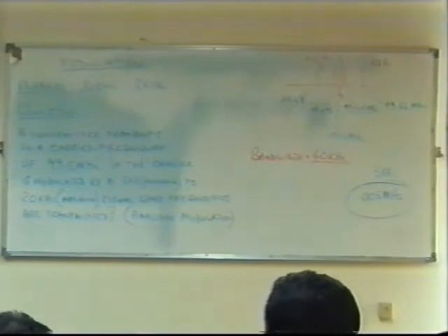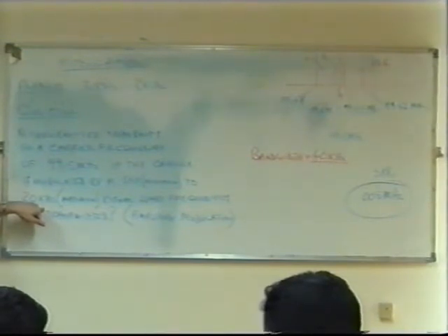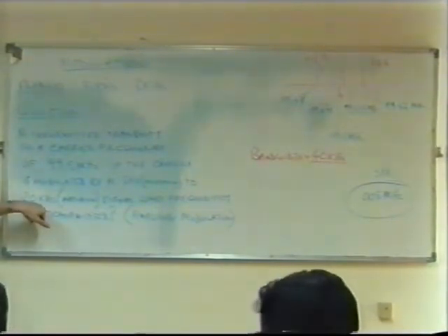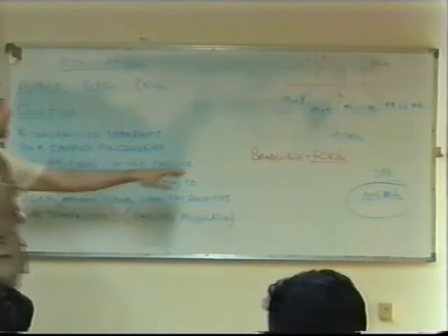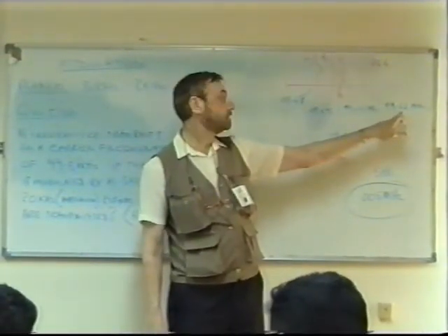The highest modulating frequency, and double it. Not the highest radio frequency, of course. The highest radio frequency is this, transmitted. Don't double that.